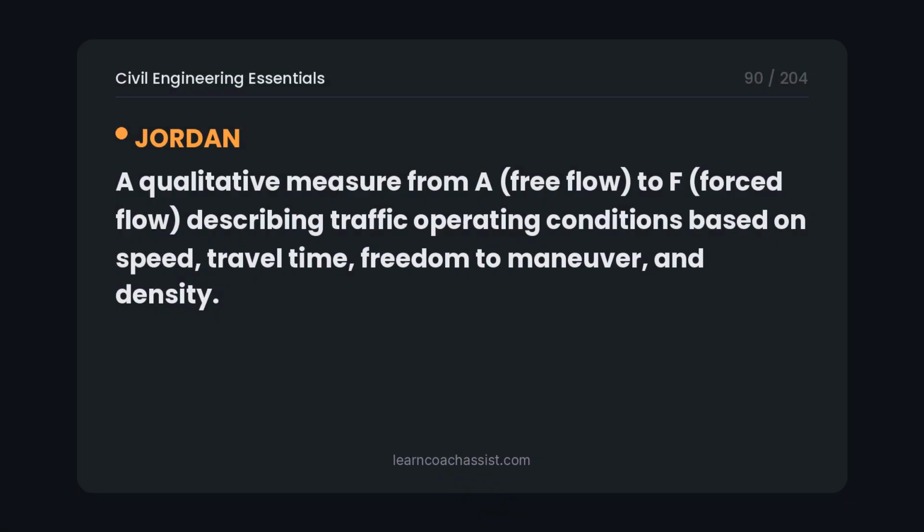What is level of service, LOS, in traffic engineering? A qualitative measure from A, free flow, to F, forced flow, describing traffic operating conditions based on speed, travel time, freedom to maneuver, and density.